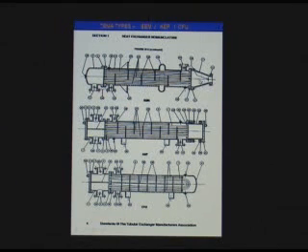You could actually have pure axial flow, where this bonnet head was actually a cone, so you would flow into the tube field through a conical head, out through the tubes, and then either exit with a concentric cone, which you have here, or you could potentially have an eccentric cone if you were condensing liquids. That way you would not trap liquids in the outlet channel.